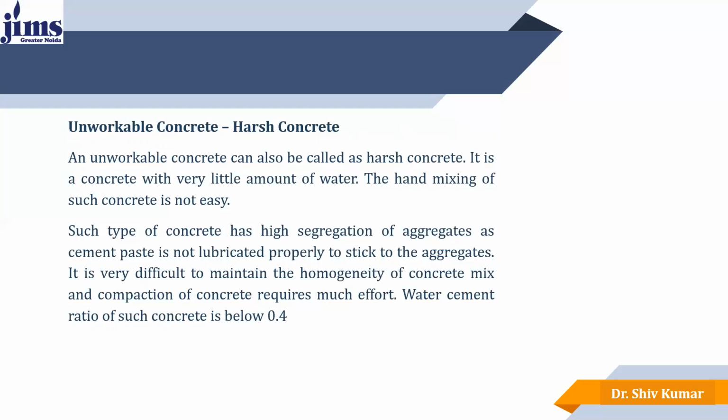This is also known as harsh concrete. Such concrete has high segregation of aggregates, as the cement paste is not lubricated properly to stick to the other aggregates. It is very difficult to maintain the homogeneity of such a concrete mix because the water cement ratio is too low. It is below 0.4 for such type of concrete.